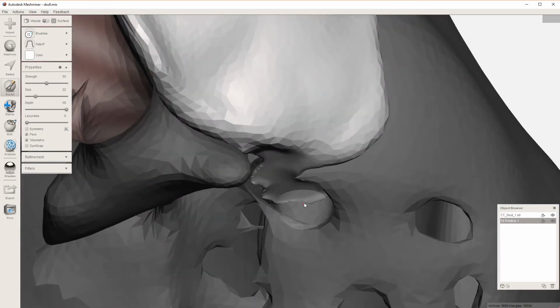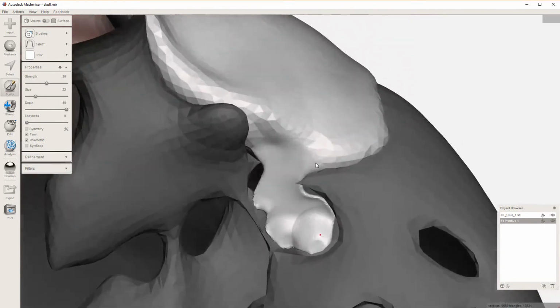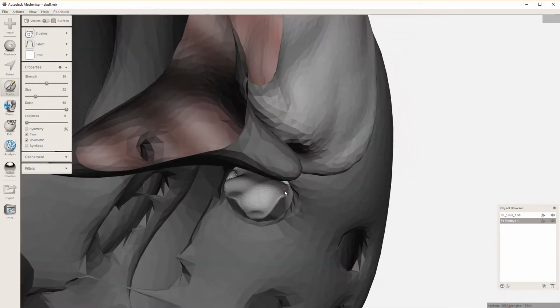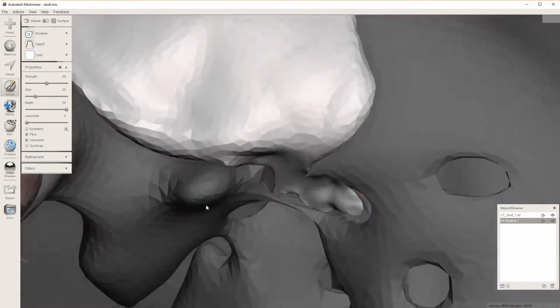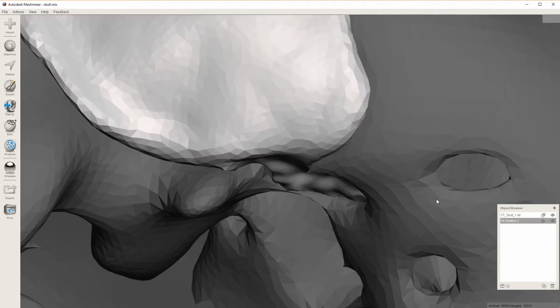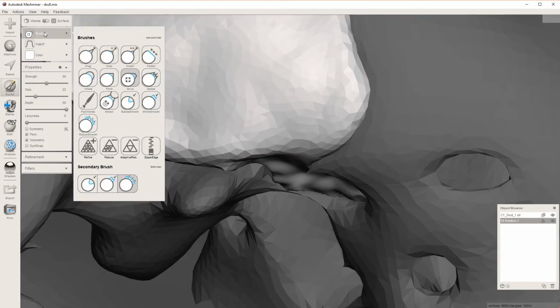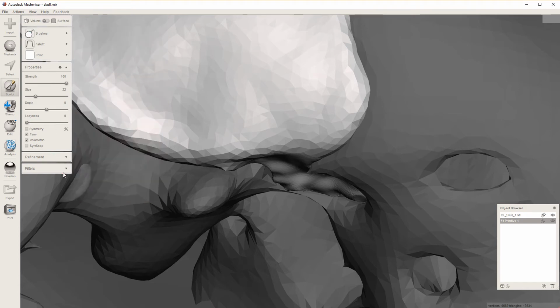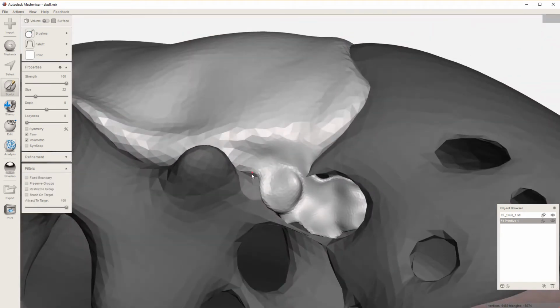The move also would work. I'm just going to move that down. Kind of like that. Now that is matching that little area right in there, and it looks good. I'll turn on the target again and do the same thing. Sculpt, draw, attract to target all the way on, and it should kind of suck right to the edges right there.